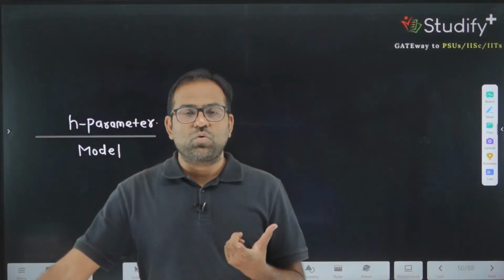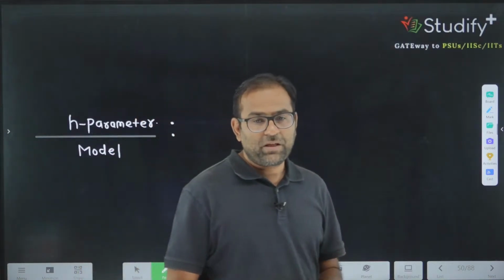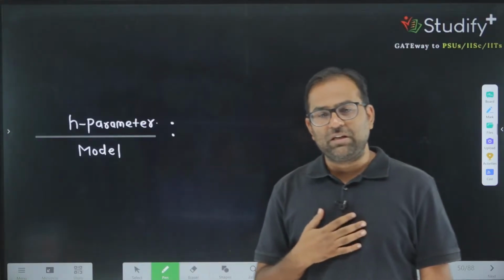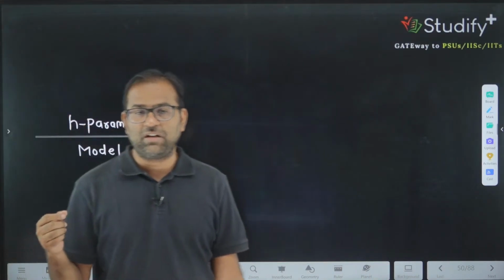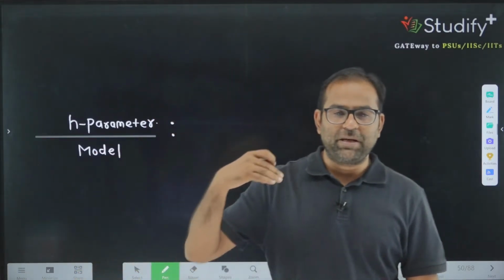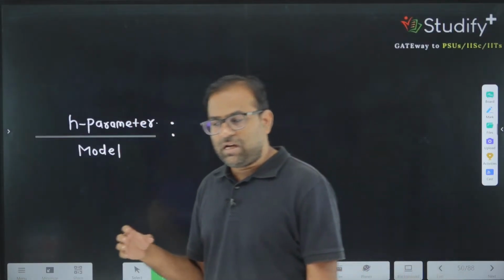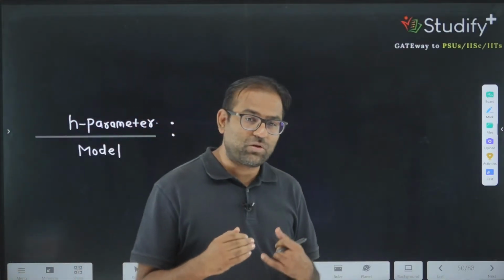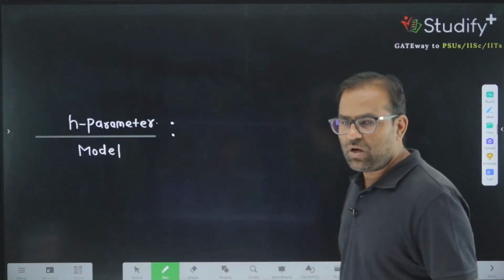Some parameters are known as input impedance, that will tell you how your amplifier will behave, means behavior of amplifier with respect to loading. Some parameter will give you the output impedance. The output resistance will tell you how fast, means in case of capacitive coupling or for the case of maximum power transfer you can adjust the load. And the H parameter model will give you the information about the voltage gain, current gain. So this is very important to analyze all kinds of transistor.